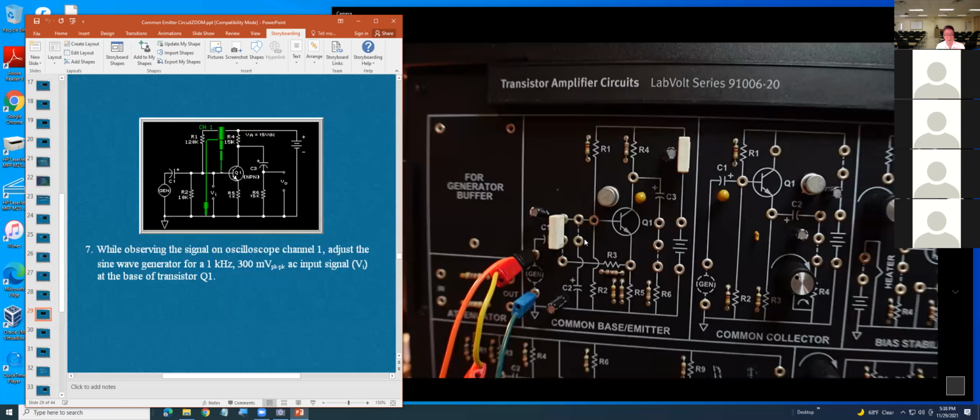Yeah, basically, I skipped that from the beginning. They will be telling you to measure the VB. So basically, you want to measure the VB: connect the high side to the base, low side to the root. Then they want to measure the VE, same thing: connect the high side of the meter to here and the low side to the root.